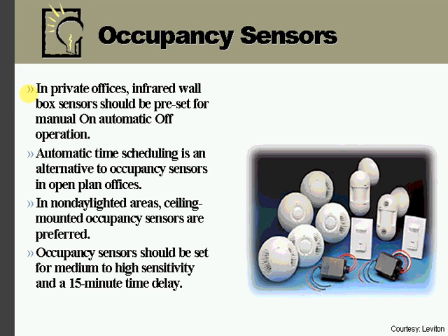I actually did a little test on myself a few years ago in a private office. I set the occupancy sensor for 6 minutes. Lights went on and off on me all day. Next day I set it for 8 minutes, and it went off a couple times in the day. Third day, I set it for 10 minutes, and it still went off on me once or twice. 12 minutes the day after that, I actually didn't have any of the quote-unquote false triggers. So I would recommend that you set your occupancy sensors for about 12 minutes.